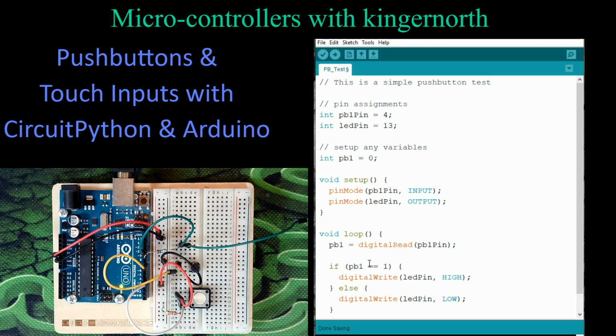And that's just is equal, not a not equals. You're doing a comparison between these two values. But Arduino allows us to do a short form, and so do most languages. If we don't fill anything in afterwards, it just assumes that you want it to be a true, and true is 1. Anything other than 1 is false. Down here, if it's true, we do whatever's first in the if statement, and that is we're going to set the pin to high, in other words, turn on the LED. If it's false, and that's the else, in other words, if it's not true, we're going to turn off the LED.